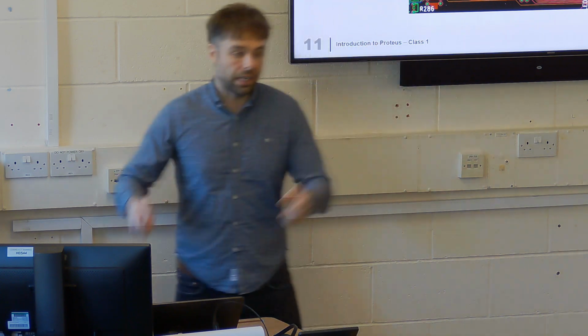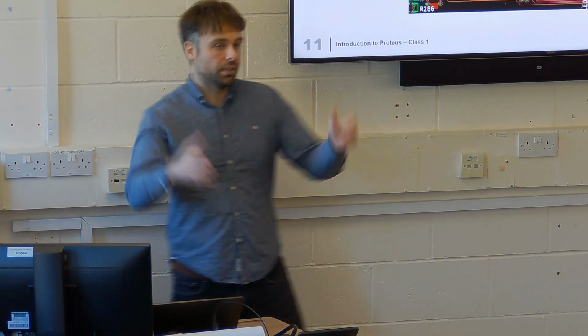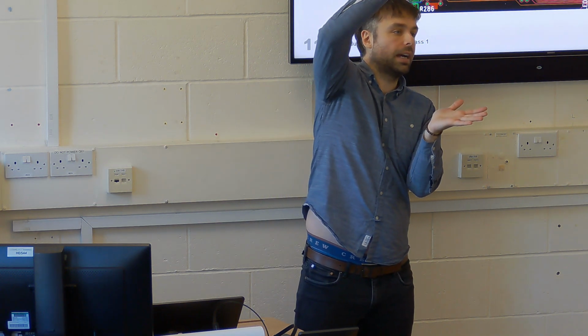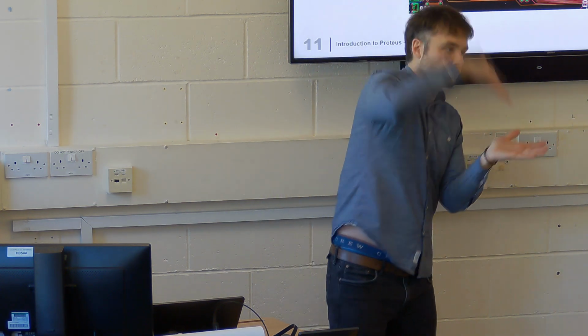Yeah. ICs and components all come with reflow profiles. So in industrial automation, you'd actually put it in the one end of a conveyor belt, and then it'll be in a big long machine that gets zoned, and it's like zones of heat. You know what I mean? And then that takes it up in temperature, soaks it at high temperature, comes down at a controlled rate, and then by the time it comes out of the conveyor belt, it's soldered.